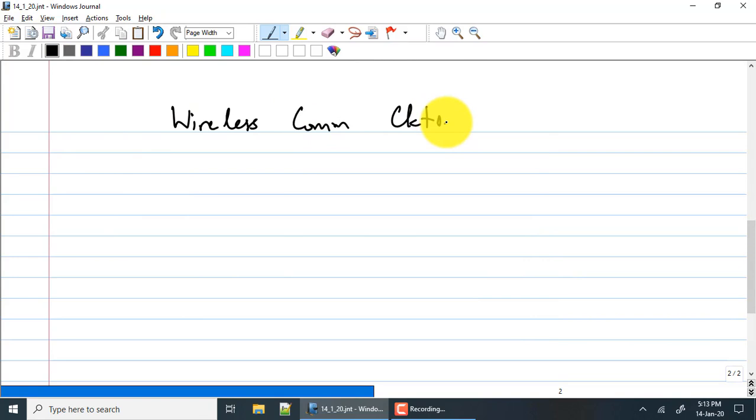In most of these wireless communication links, it is normally the receiver that is tougher to build compared to the transmitter. So you will naturally see majority of courses that deal with communication circuits or RF circuits, they deal with the receiver. Majority of research happens on receivers. We will also look at transmitters, but we will focus on the receiver. Even in your projects, as you can see, the LNA, mixer, and VCO will all go towards implementing a receiver.